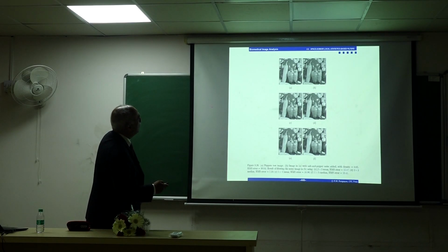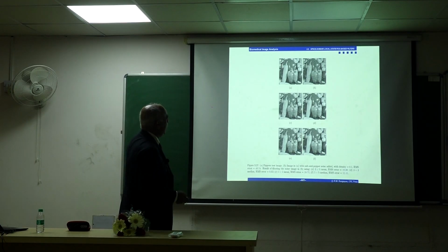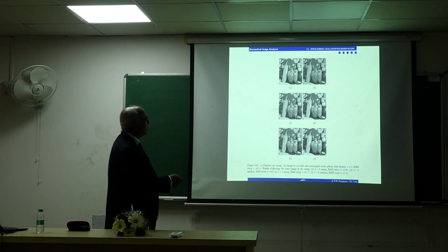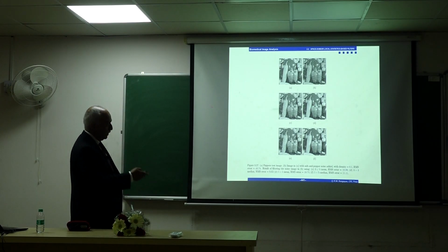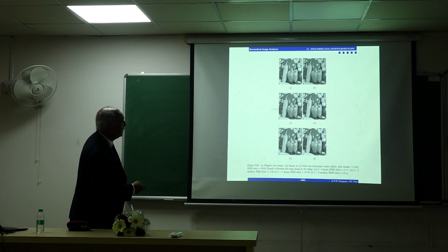So again, different types of noise. I'll skip to the salt and pepper. This is where the median works really well. The mean fails and the median works. The others, it's a little difficult to see.